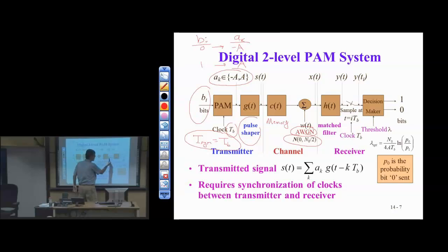What that really means is that we run an averaging filter and take the last value that comes out of that. This averages the received signal for one symbol period, giving one value. So I take one value per bit duration. Remember, bit duration is the same as symbol duration.